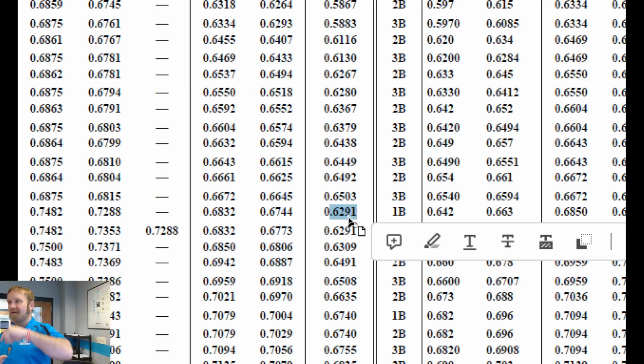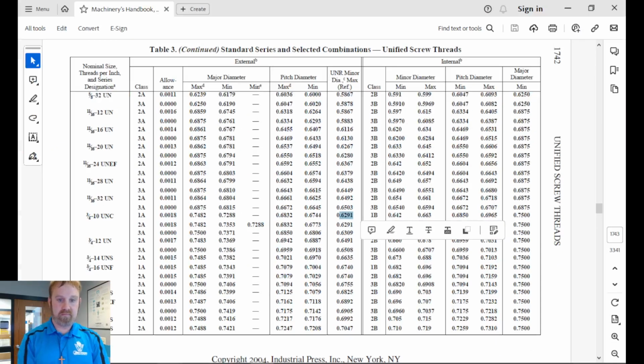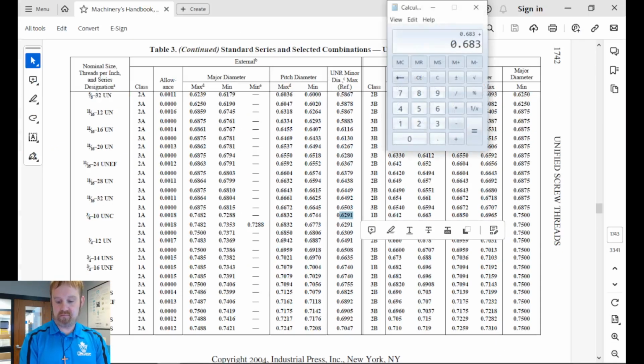Not that it's not calculated on the manual side, but I consider what I do out here a little more calculated a lot of times than just going a little more and seeing if the nut fits. I've got a thread pitch mic. I know my thread pitch needs to be somewhere between .683 and .674. So I want to be about .678.